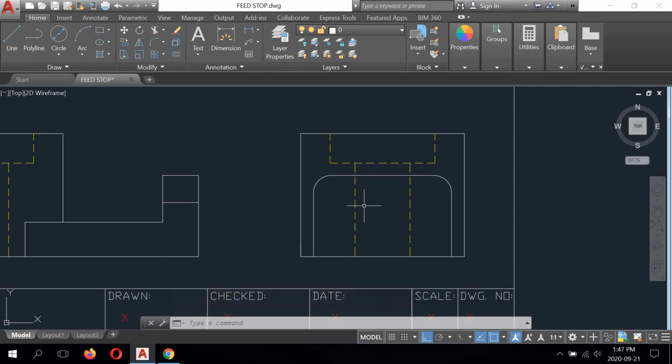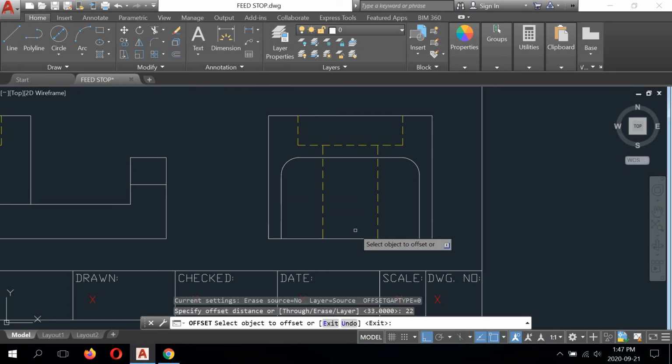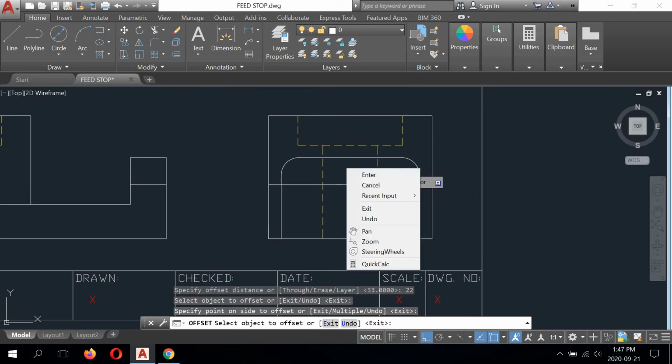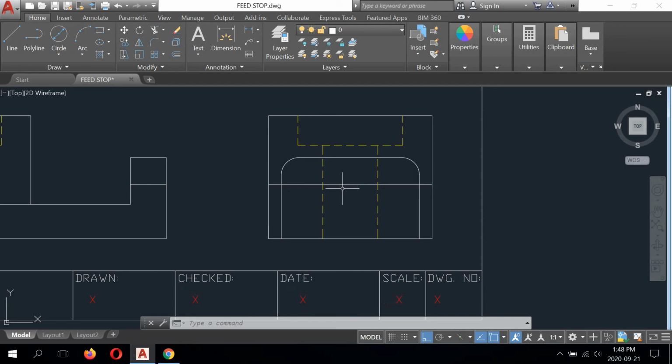Pretty slick. All right. There's another slot going vertically through the flange, so we need to find the location for that. So we're going to offset from the bottom horizontal line up 22. So here, at the midpoint of that line is going to be where we're going to draw our next circle. So this is a radius circle.